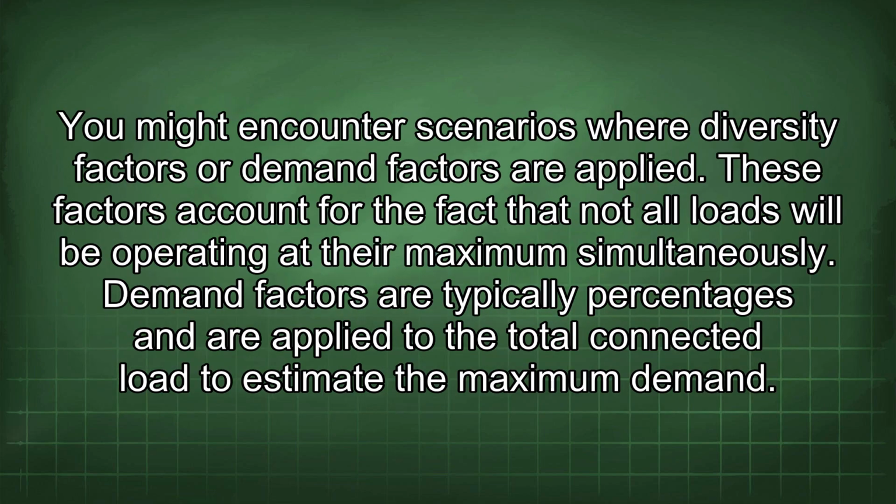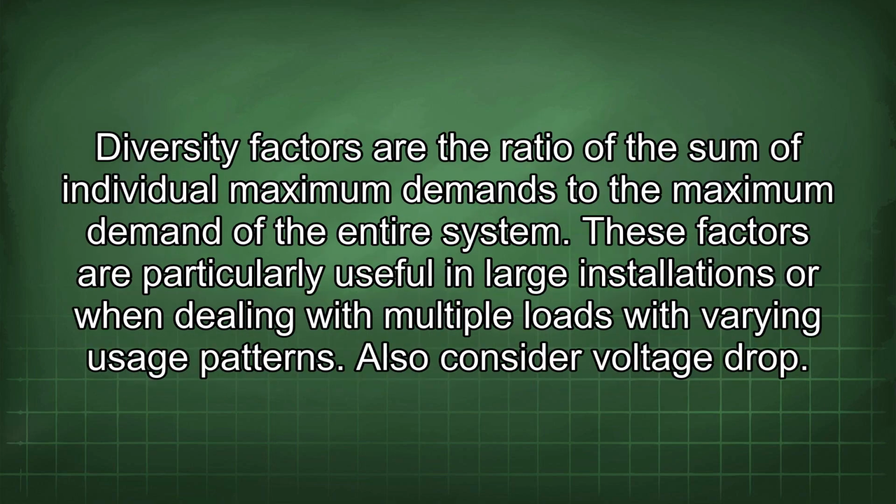You might encounter scenarios where diversity factors or demand factors are applied. These factors account for the fact that not all loads will be operating at their maximum simultaneously. Demand factors are typically percentages and are applied to the total connected load to estimate the maximum demand. Diversity factors are the ratio of the sum of individual maximum demands to the maximum demand of the entire system. These factors are particularly useful in large installations or when dealing with multiple loads with varying usage patterns.